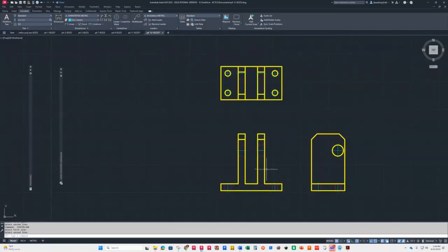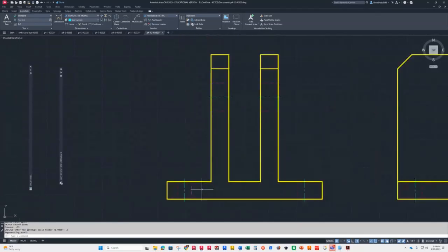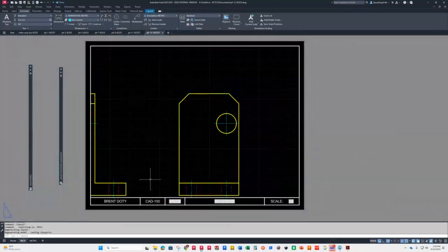Okay, now since I can't see those, even though it's on an inch drawing, like I said, a lot of times line type scale should really be 0.5 for inch drawings, so that, notice it looks okay there. That's pretty cool. Over to inch. Yep, it's going to show up.